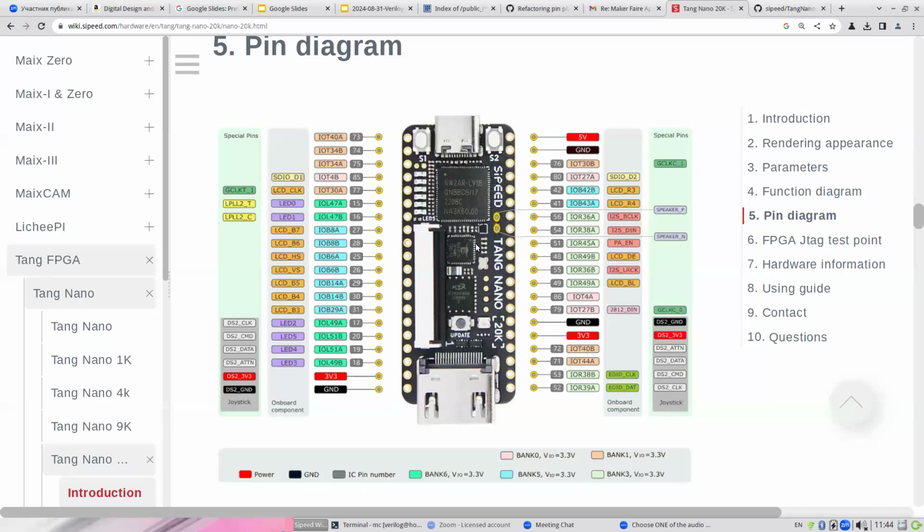And then we are using connection to its own speaker using signals I2S left right clock, PA enable, I2S BCLK, I2S DIN, but we don't need to connect anything externally. We just connect the speaker to those two little holes.